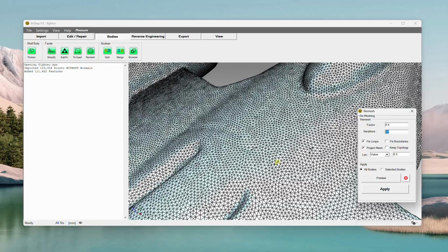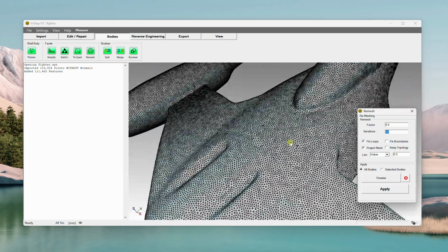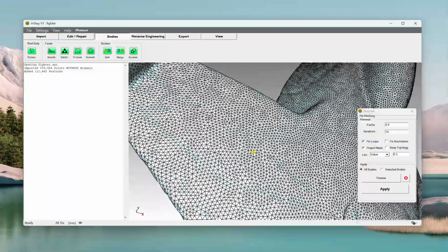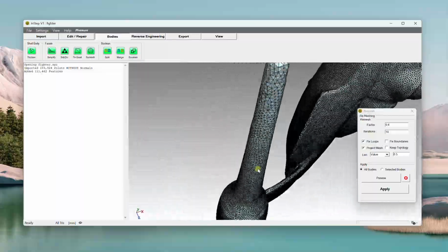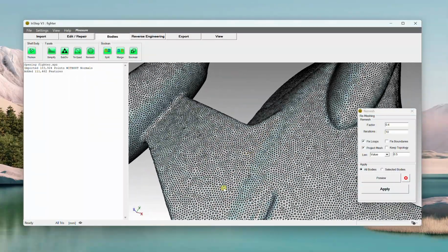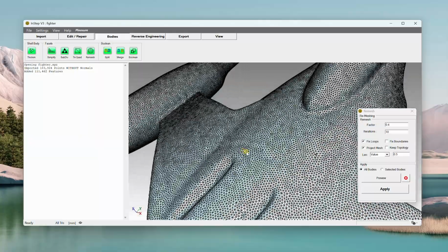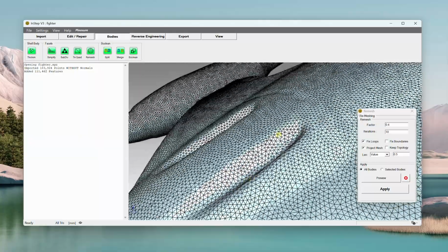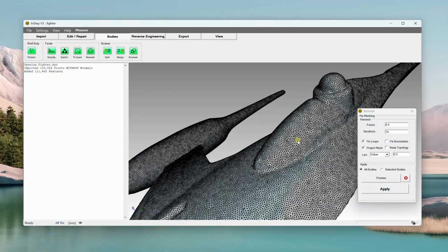We can play this a little bit more and probably end up with 20 or something, but for the purpose of this, we actually now have a very nice clean mesh, and with just a few more iterations of that, this would be a good source mesh. I wouldn't necessarily use it for CFD, but as a general mesh, this would actually be quite useful.